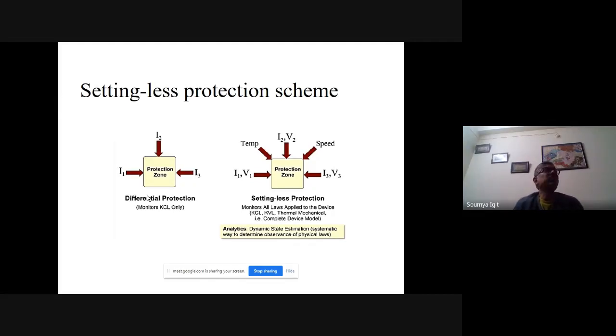Similarly, on contrary, I told you regarding the overcurrent protection as per the coordination time interval and the total relay operating time. Differential protection is straightforward when you go for a unit based protection with the reliable communication infrastructure.